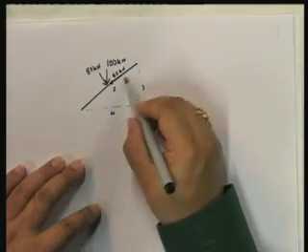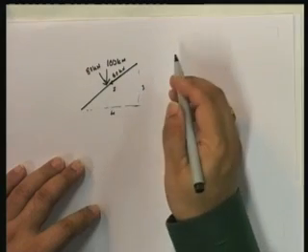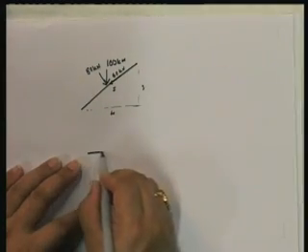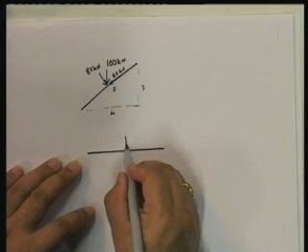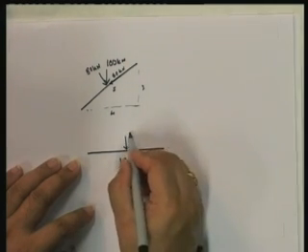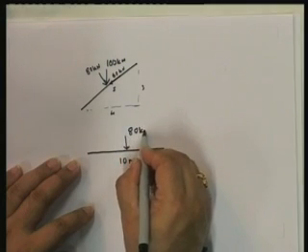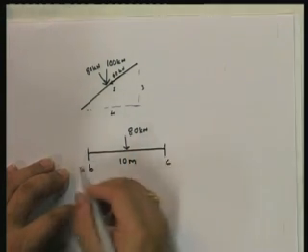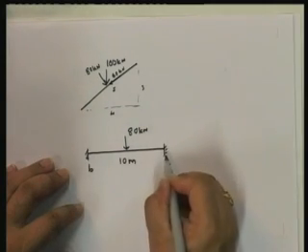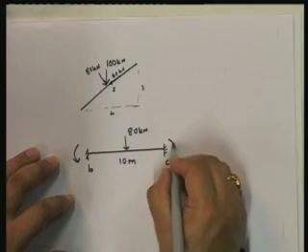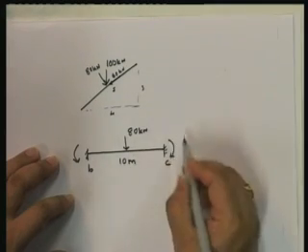Now the horizontal component, since the member is actually rigid, does absolutely nothing, and therefore this problem essentially becomes one where you have a 10 meter member with 80 kilonewton, and we have to find out for B and C what the fixed end moments are, and that we know is equal to PL by 8.